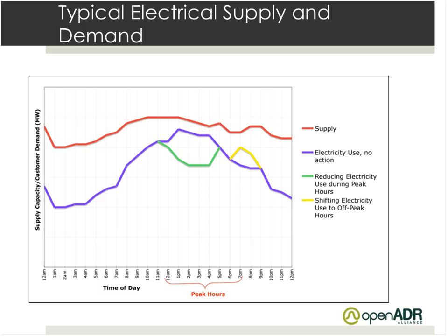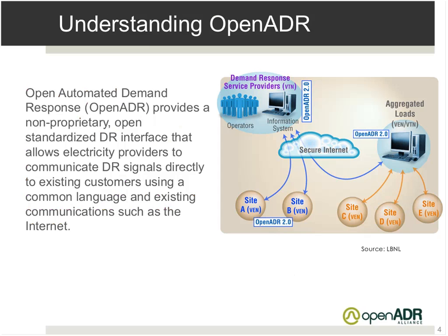energy-constrained markets. The concept of OpenADR, Open Automated Demand Response, emerged about 10 years ago after the California energy crisis during the last decade. So OpenADR is really a non-proprietary or standardized methodology for delivering price and event and grid status information from an energy service provider to a customer, which could be residential, commercial, industrial, using a standardized language, in our case, XML web services, over the internet.